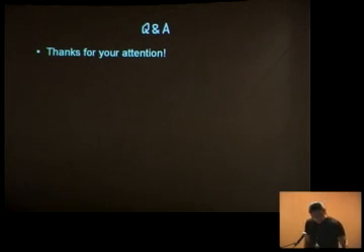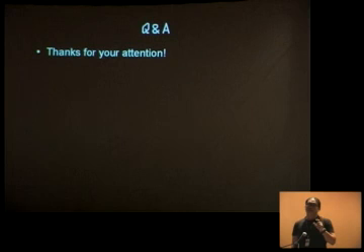Well, typically, when you're doing the signal testing, you do it with the circuit powered down, right? So there's no dangerous voltages going on, and what the testers do is put a very, very tiny current through, one that couldn't possibly damage a circuit, and then they just look for the current flowing. So when you do the testing, there's almost no interaction at all with the components, and it just extracts the connectivity of the circuit board itself.